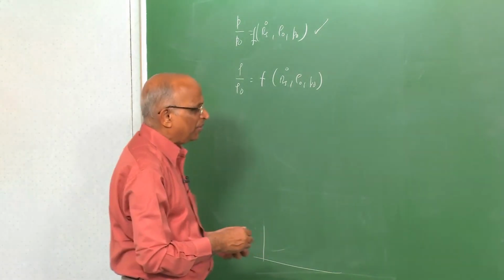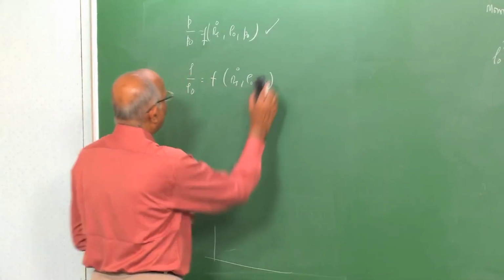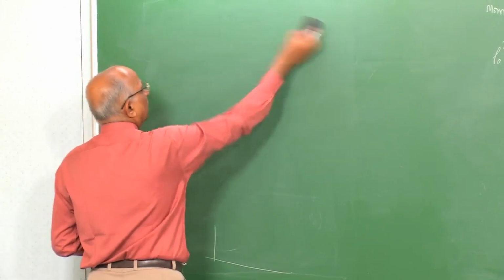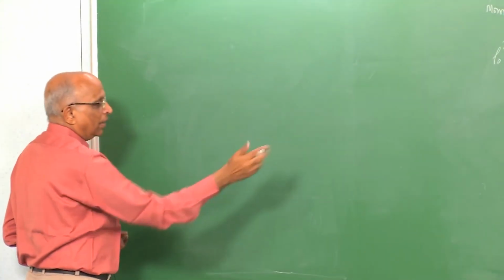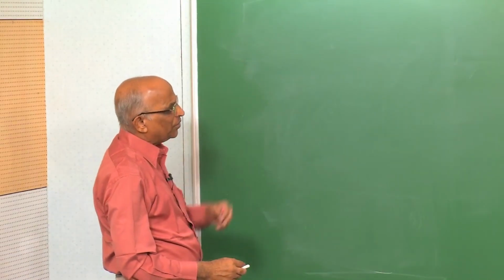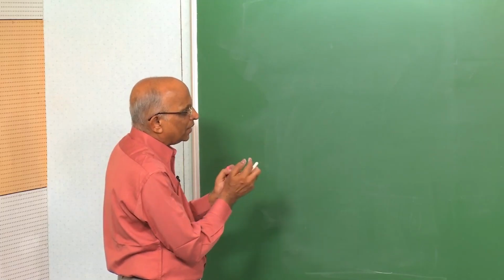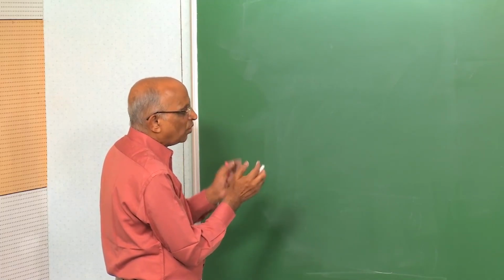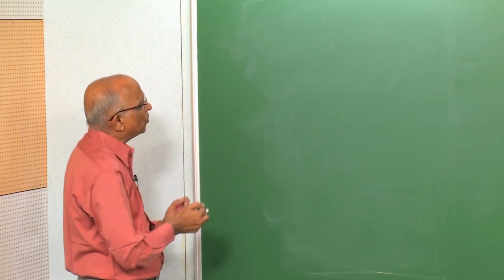To get that expression, we need to do a little more homework. Maybe I can put the Rayleigh line into the Rankine-Hugoniot equation and solve specifically for the pressure and the density behind the shock.